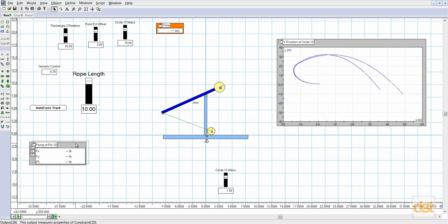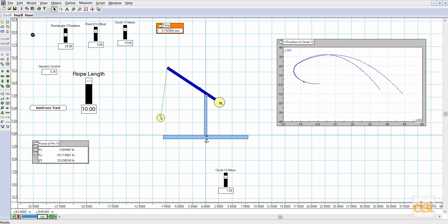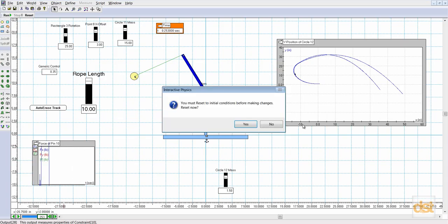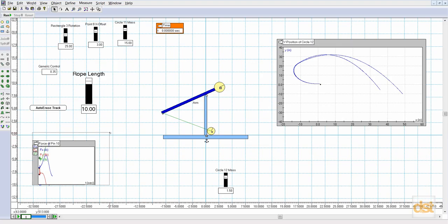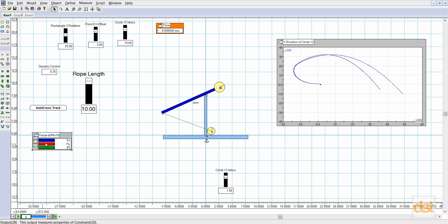Now, we can also note that we can change the display of a meter. So for example, right now, if I just run this and stop it quickly, notice how I have a numerical readout for this first default meter set. If I click on the arrow tool right here, it changes it to a graphical form. So I can see the graph portion of it. If I click it again, it changes it to a bar graph form. If I want to turn any of these values on or off, so for example, maybe I'm not interested in seeing X and Y, but only the magnitude of the force, I can just simply click FX and click FY, and it turns those off, so I'm only displaying the magnitude.